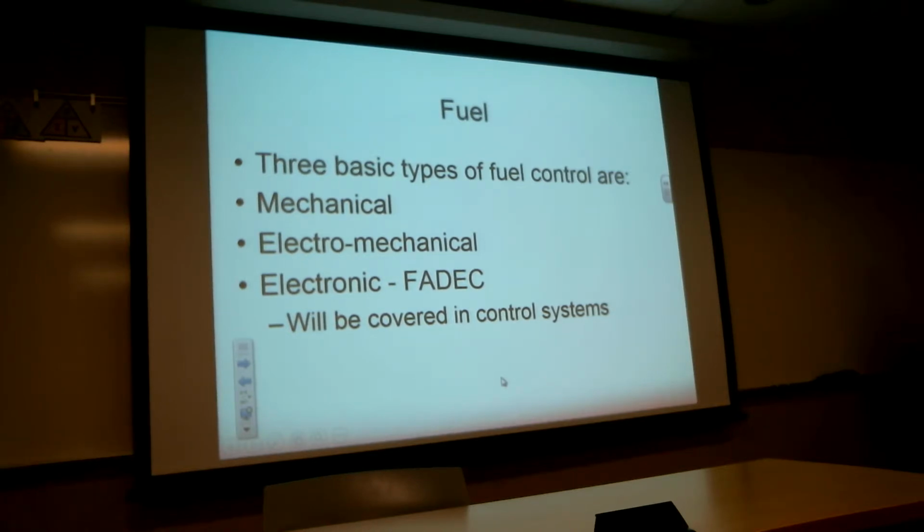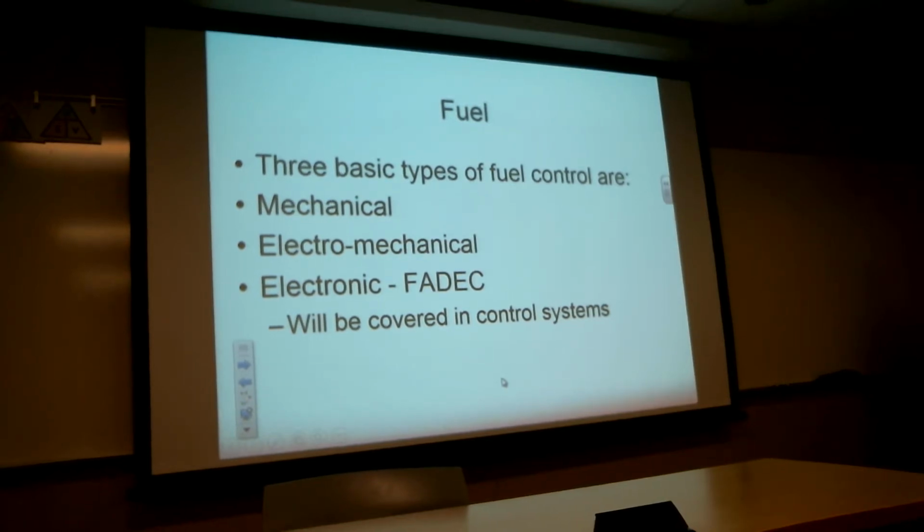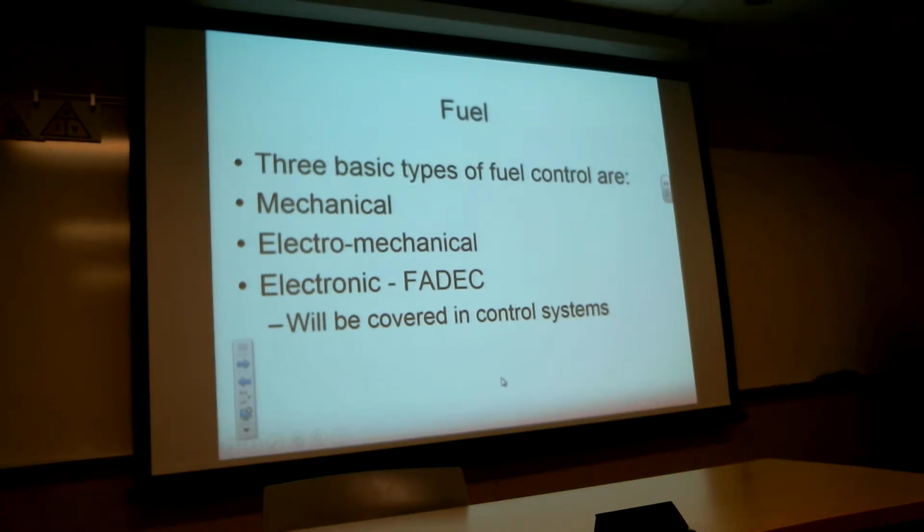Okay. So mechanical fuel controls, still a ton of them out there. If you ever have to change a mechanical fuel control, you're going to end up doing what they call an engine trim. An engine trim has to be done within certain parameters, and every aircraft maintenance manual has them. Temperature, wind conditions, and humidity have to be within those limits so that the engine produces its power.